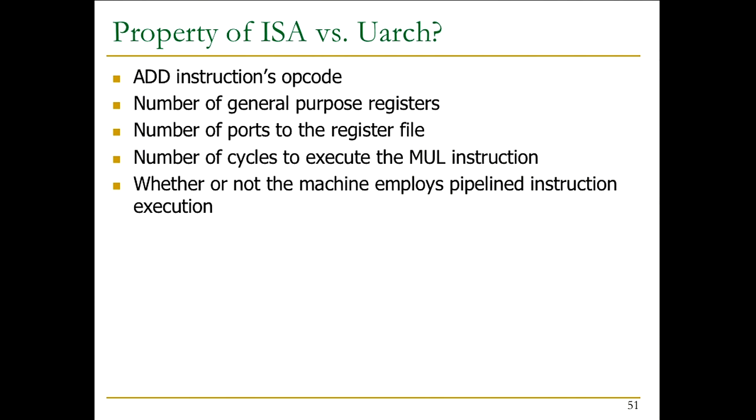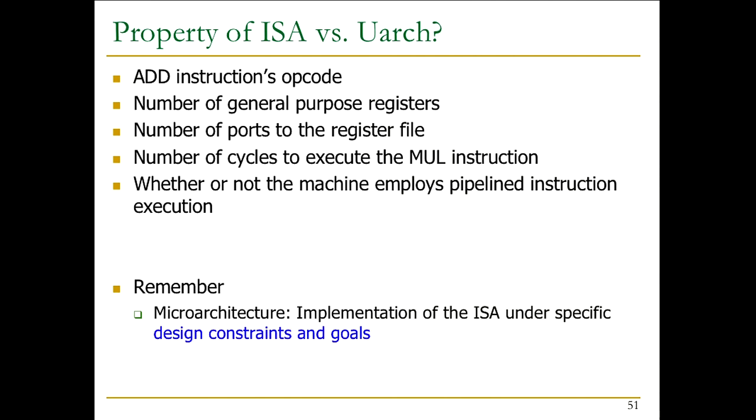Because that's dependent not only on the depth of your pipeline, but it's also the data dependencies that you have. So it's a very complicated decision, actually, and most compilers are not good at doing that. Okay, so this hopefully gives you some idea. But the last one I would consider, again, microarchitecture. Because even if you expose it by saying, oh, this microarchitecture has this kind of pipeline.